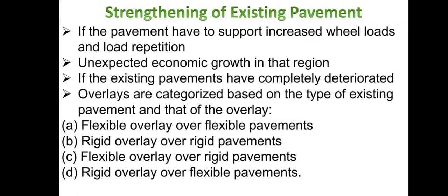Then strengthening of existing pavement. If the pavement has to support increased wheel loads and load repetition, unexpected economic growth in that region, or if the existing pavement has completely deteriorated, overlays are used. Overlays are categorized based on the type of existing pavement and that of the overlay. There are four types of overlays used: flexible overlay over flexible pavements, rigid overlay over rigid pavements, flexible overlay over rigid pavements, rigid overlay over flexible pavements.